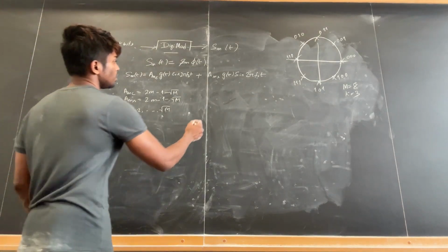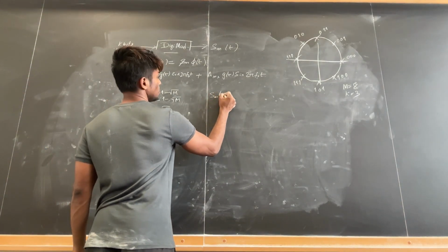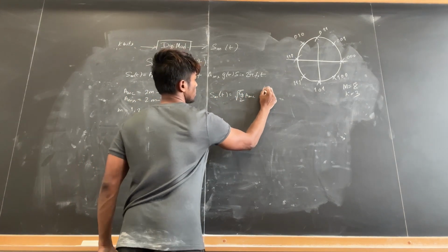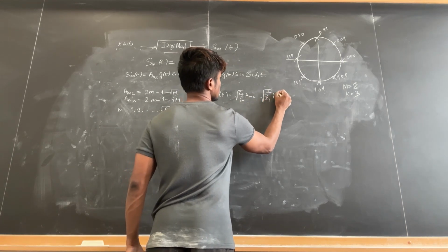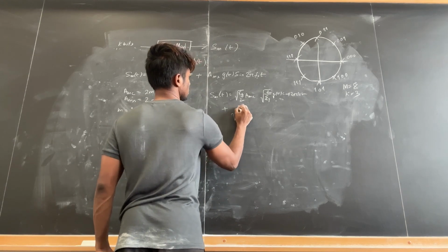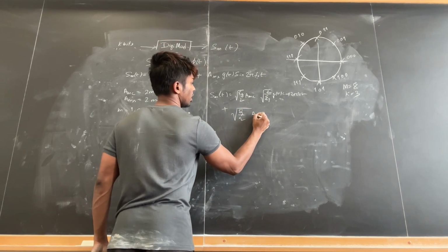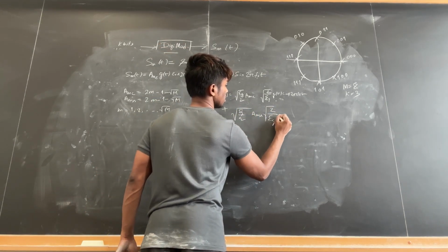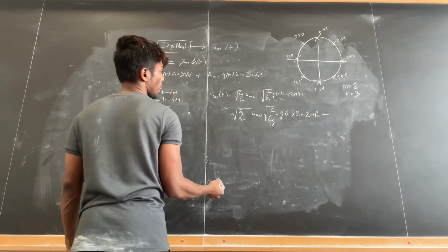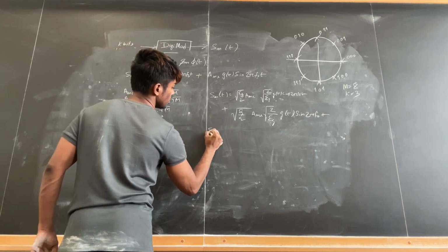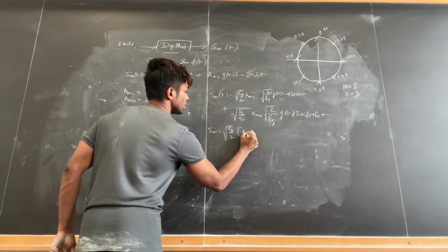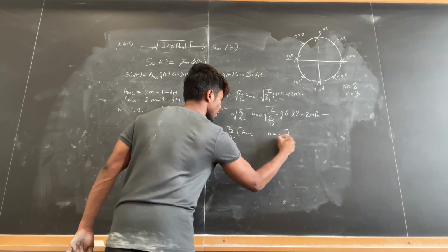So we can easily represent it as Smt is equal to square root of Eg by 2 Amc times square root of 2 by Eg gt cos part plus Ams times square root of 2 by Eg gt sin part. And then our constellation space will be given by Sm is equal to square root of Eg by 2 Amc and Ams.